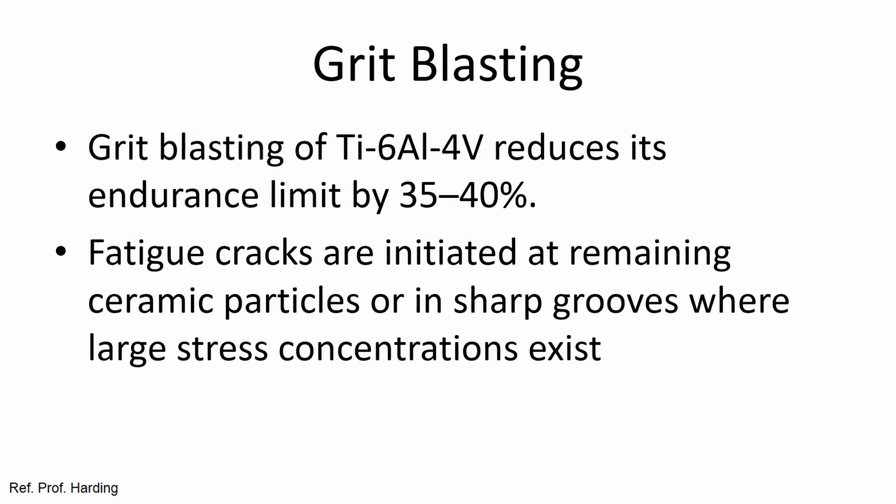Grit blasting of titanium alloy implants reduces its endurance limit by 30 to 40%. So just by merely grit blasting the surface of an implant, you reduce this endurance limit, which is the stresses it can withstand before it fractures. So nearly 40%, 50%. This is quite an effect.